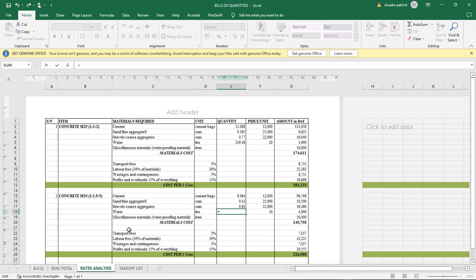About the water to cement ratio, I'm gonna be coming right here, which is equal to this. So these are the cement bags, and then I'm gonna be multiplying it with 50 because I need the kilograms, so that this water will be in liters, and then I'm gonna be multiplying it with 0.45 as we've done before, and then I'm gonna be having 181 liters of water, and I'm gonna follow the procedure.